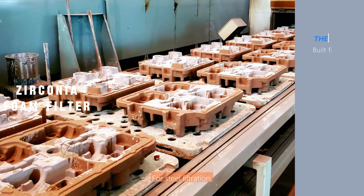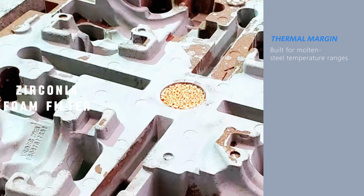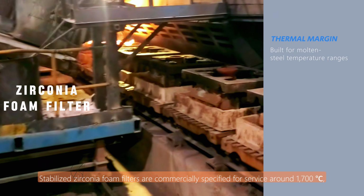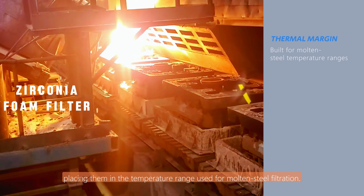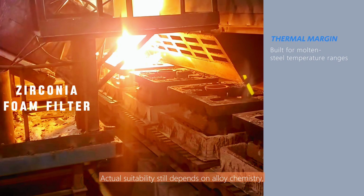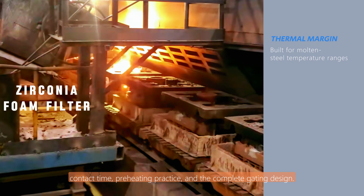For steel filtration, the ceramic body must remain functional while the incoming melt is at casting temperature. Stabilized zirconia foam filters are commercially specified for service around 1700 degrees Celsius, placing them in the temperature range used for molten steel filtration. Actual suitability still depends on alloy chemistry, contact time, preheating practice, and the complete gating design.